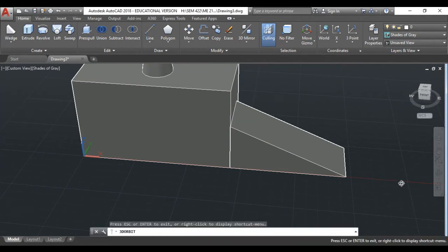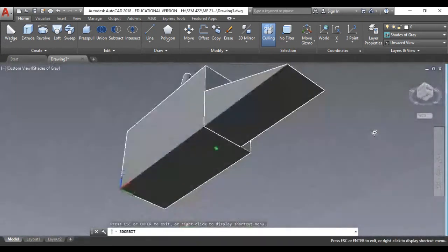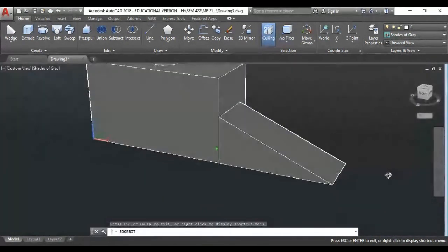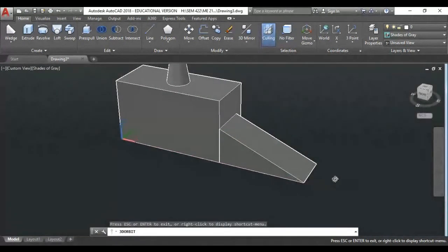Very simple. Here is the key. Look carefully, guys. Everything is beautifully there. You got this one? And this is one of the most important things. Sometimes, guys, we find difficulty to draw the wedge in the location. So what we do is draw the wedge outside of the object and then use the alignment to locate it in its original place.